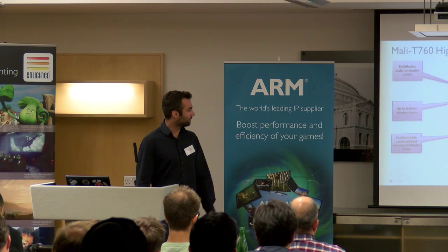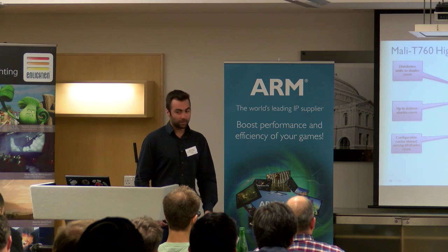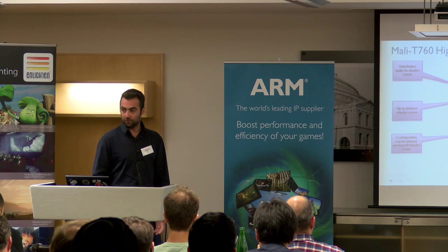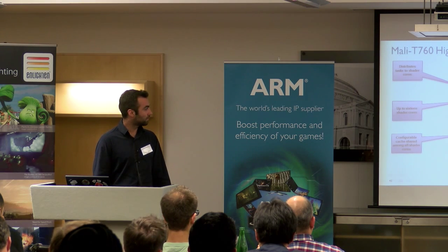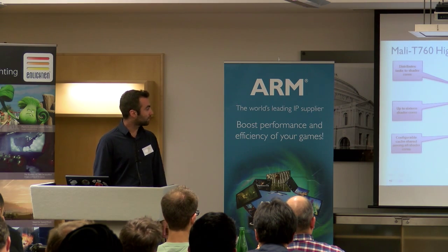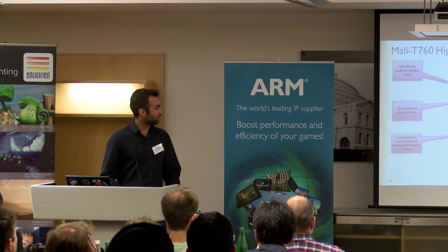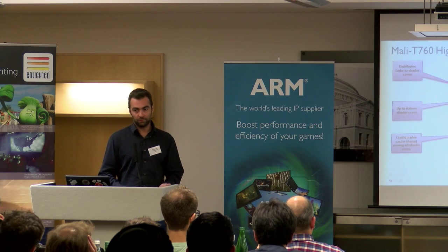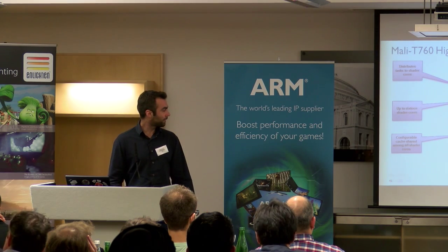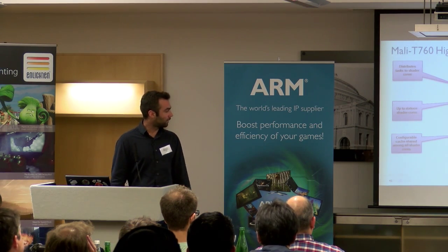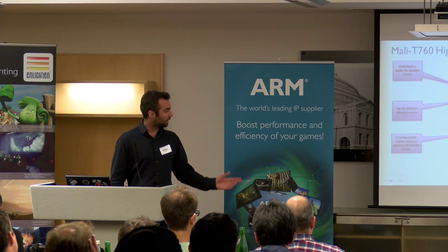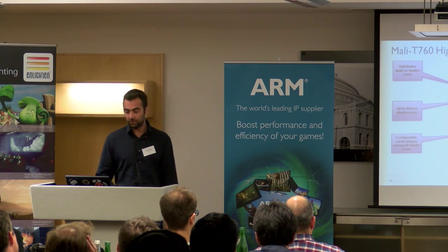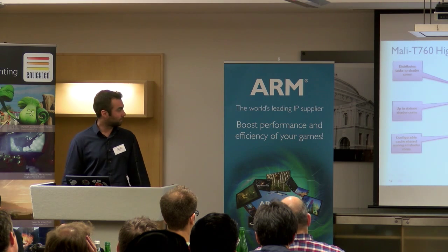Then we have the advanced tiling unit, which is making sure that we have an efficient mapping of all the geometry primitives to tiles. We have the memory management unit, which is doing the standard transformation between virtual and physical address space. And of course, the appropriate number of L2 caches and an ACE-Lite interconnect, which is giving you I/O coherency.